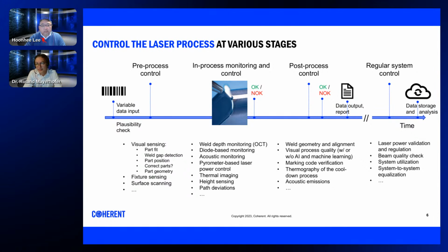If we step one process step further, so we will actually do the laser marking, there's a lot of technologies available to get the data from the process itself, mainly used for welding, like the OCT, the optical computer tomography, but also the diode-based monitoring and acoustic monitoring is a nice tool to really get a fingerprint of the process and an immediate feedback after the process if it was like expected or maybe off and needs to be corrected. There are more possibilities to check things during the process, but they typically don't apply to laser marking.